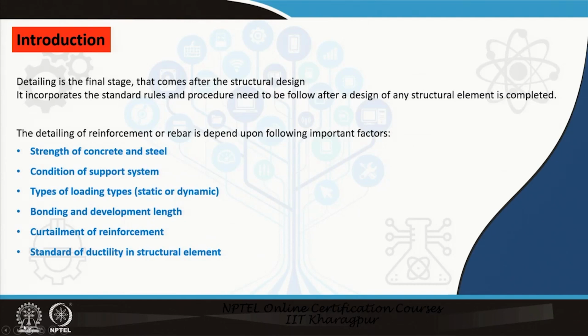Because of that, the system of detailing may change. The type of loading system, maybe a static loading or a dynamic loading. We have to check what kind of load may be applied to a structural element in its lifetime. So, based on that there will be a slight change in the detailing.